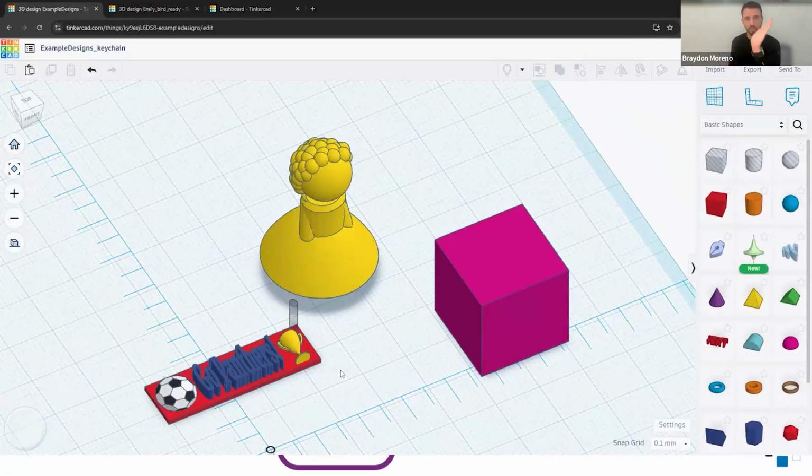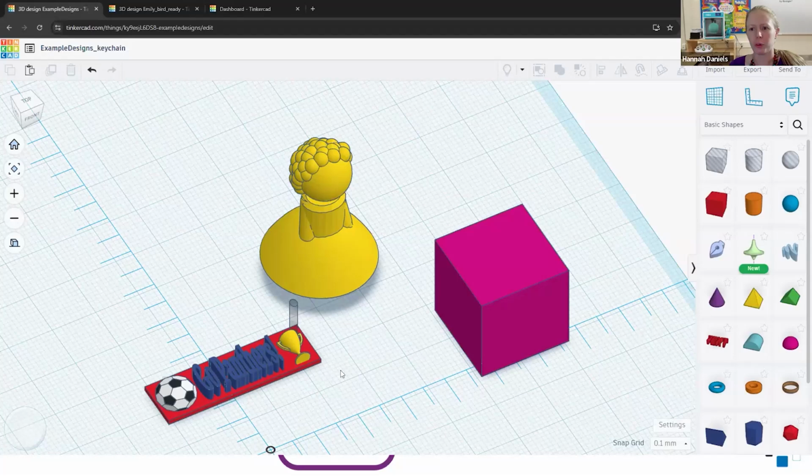Like, is a 45-degree angle a good? 45 is the classic. It depends a little bit on your printer. I've noticed higher speed printers like our E4 out there, even a little steeper than that is better, you know, 50 to 55. But with supports, you can do full circles.